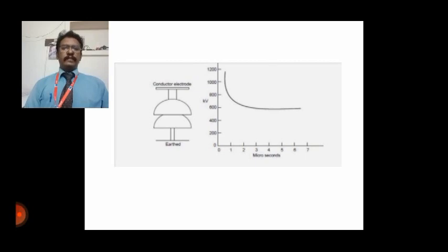This type of surge diverter is perhaps the simplest, cheapest and most rugged one. You can see in the figure. This is such a gap for bearing bushings and breaker bushings. This may take the form of arcing rings. Normally, regarding the breakdown characteristics of a rod gap, for a given gap and wave shape of the voltage, the time for breakdown varies approximately inversely with the applied voltage. You can see the graph.